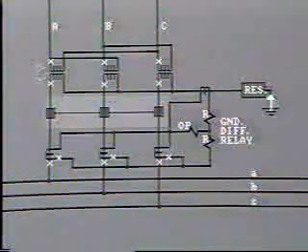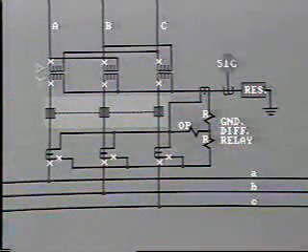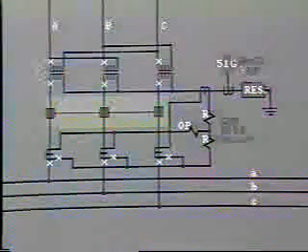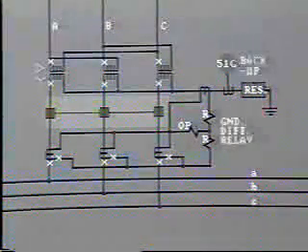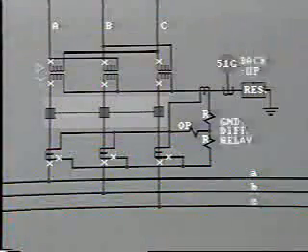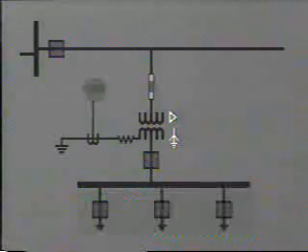Quite often with this arrangement, an additional time over current ground relay, 51G, is installed in the neutral. This acts as backup for the transformer ground differential, and also as backup for ground faults out on the feeders. It must be correctly coordinated with protection on the feeders.